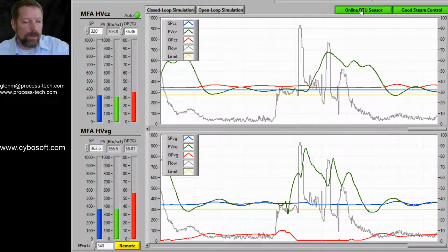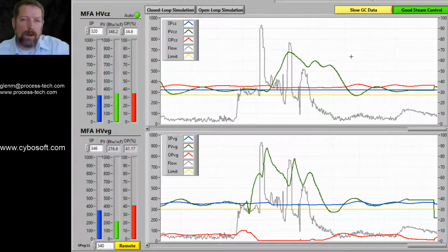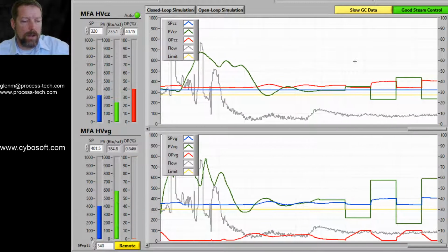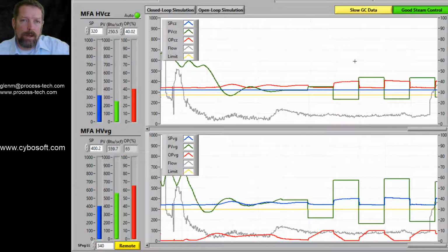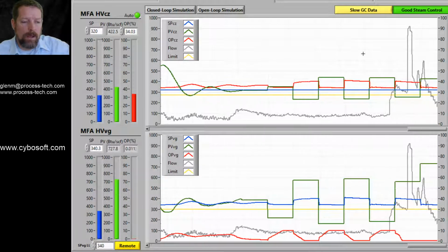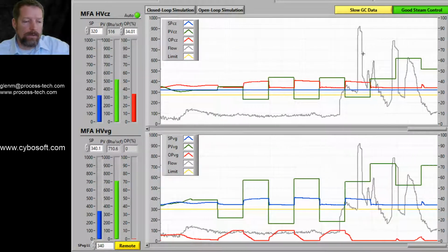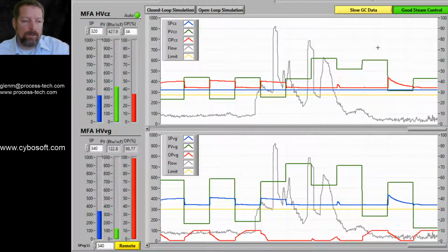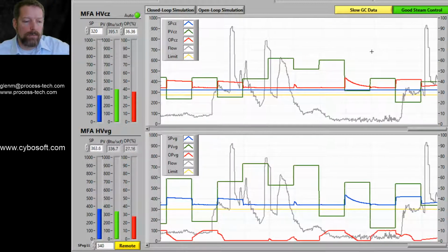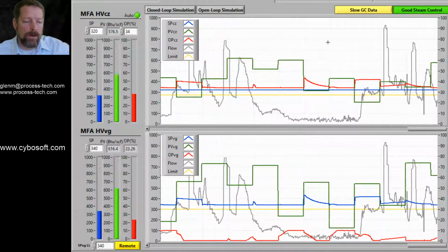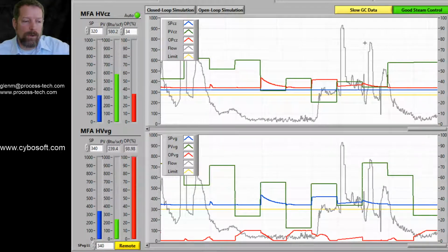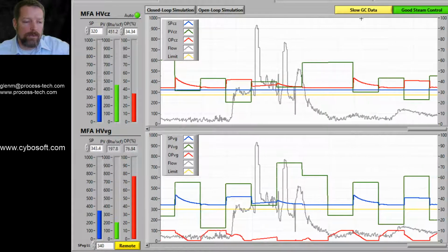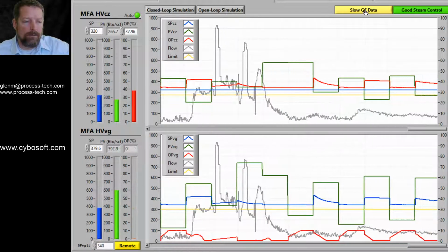Let's just flip this switch real quickly, show you what happens if you use a gas chromatograph, as many of our customers invested in GCs for subpart JA compliance in 2015 for reporting to speciate. A gas chromatograph is simply not fast enough from a process control perspective to give you the resolution that you would rely on for doing good process control. So although a lot of customers have GCs and they work great for what they were intended for, getting a fast net heating value is just simply not a viable solution.